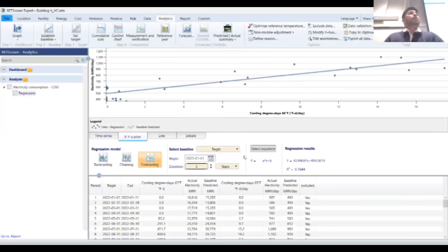There you go. I have this regression equation, and again, I'm not going to get very detailed with what the numbers look like, what the details are, but all I want you to see is that it's created a correlation between electricity and cooling degree days, and there are certain periods or certain consumptions that are up and down of this line. It just shows that the correlation is not that great for those points. The next step is to have a cumulative sum.